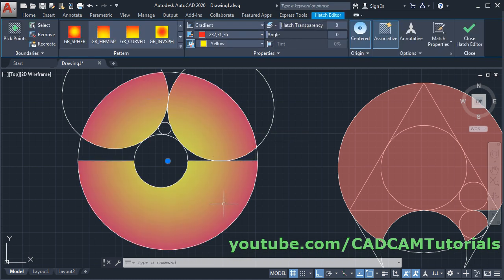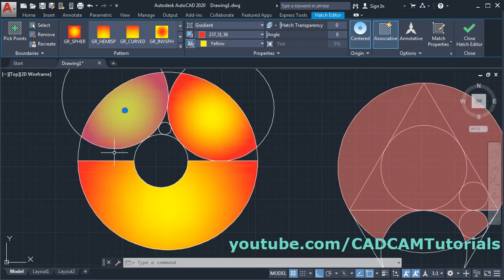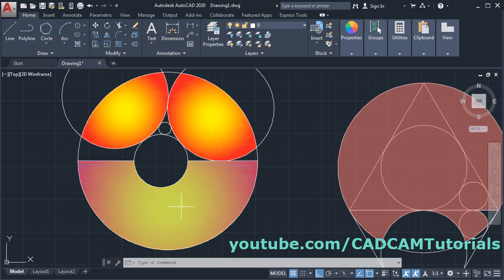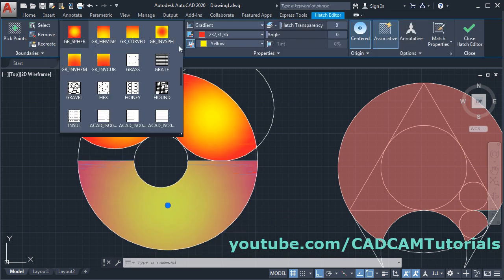Suppose I want to change this hatch and keep this hatch as it is, then I will have to separate hatches. To separate this hatch, click on options and click on separate hatches. So each hatch will be individual. Then click on OK. Now here you can select this hatch and you can change its pattern.